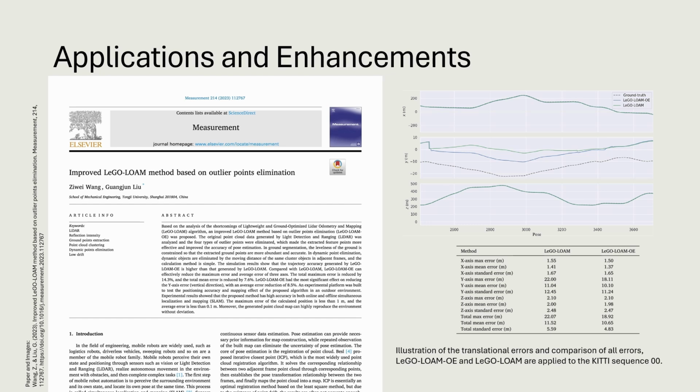This pre-filtering of features enhances the point cloud before it is used in the odometry and mapping steps. The remaining feature points more likely belong to static objects, which are captured in multiple sweeps and are stable and reliable. The impact on the system's performance is also measurable in the simulation with the KITTI dataset. The translational inaccuracies are reduced, especially the error in vertical direction is decreased. The generated map reproduces the environment with clearly outlined objects. The outlier elimination LeGO-LOAM is therefore another simple and plain way for improving LeGO-LOAM.